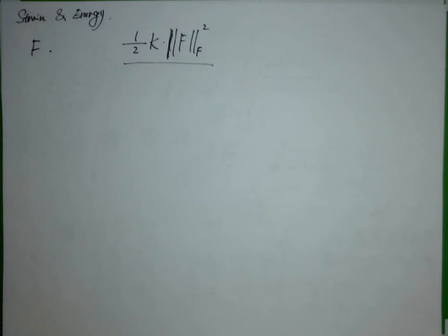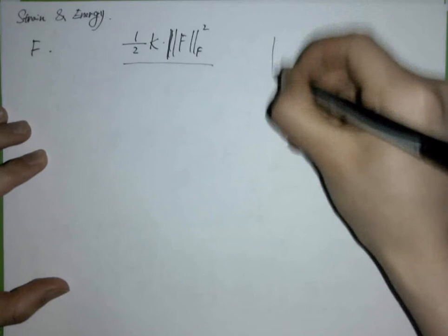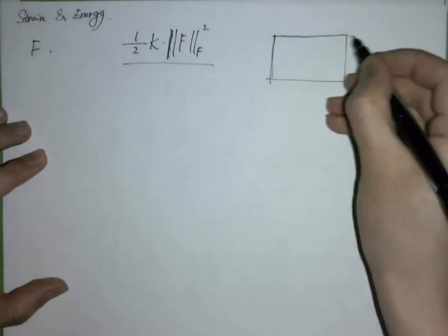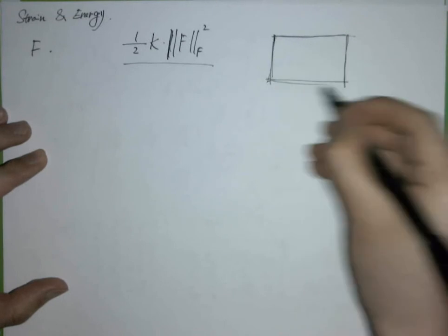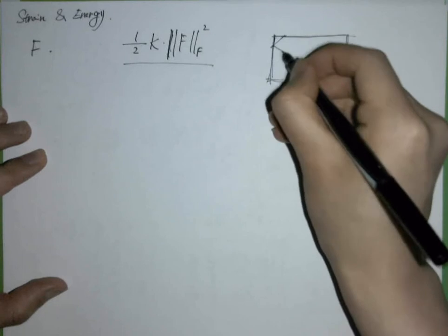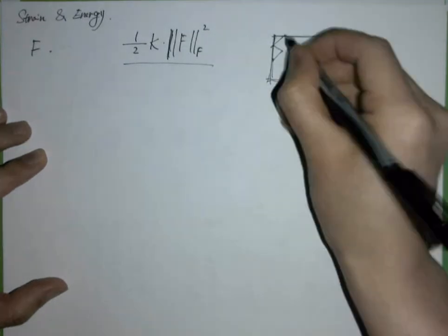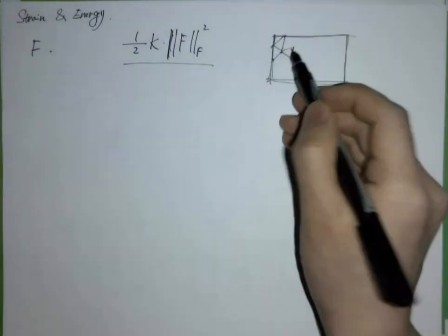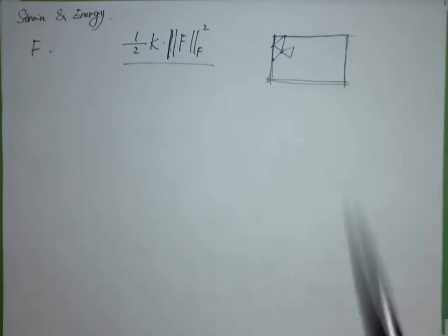It's not completely useless because in some cases, like image warping or some 2D image synthesis, if I fix the boundary of the entire image as a hard constraint, so all the vertices on the boundary are not allowed to move, then every element inside is allowed to collapse into a point, because the boundary will fight against it.